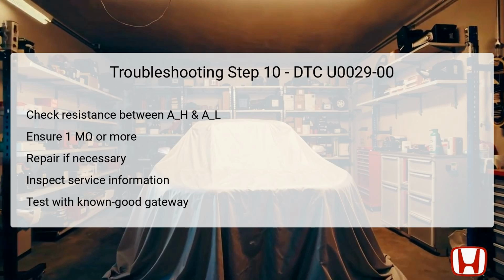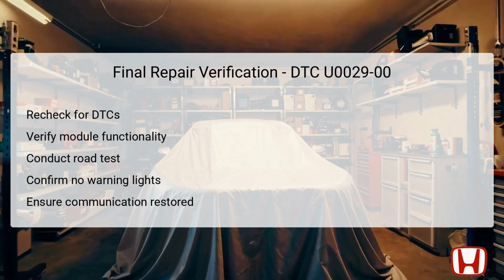Additionally, consult any authorized service information for further guidance related to DTCs or symptoms encountered. If repairs are unsuccessful, testing with a known good real-time CAN gateway may be required to re-establish proper communication across the vehicle's systems. After conducting repairs for DTC